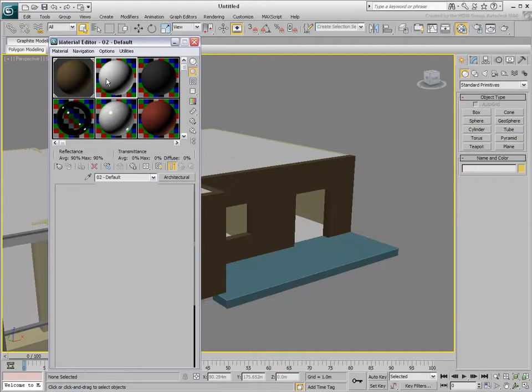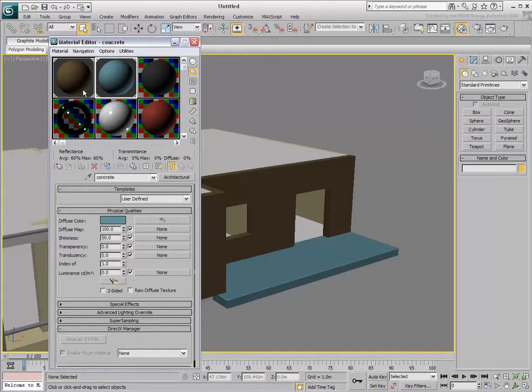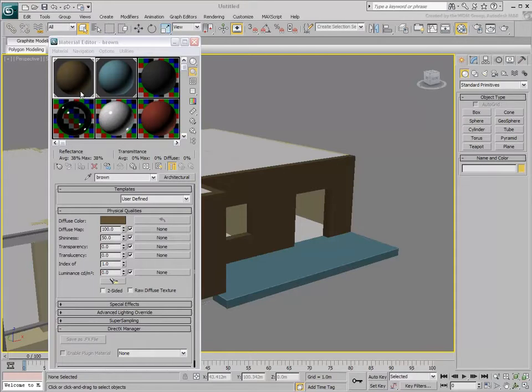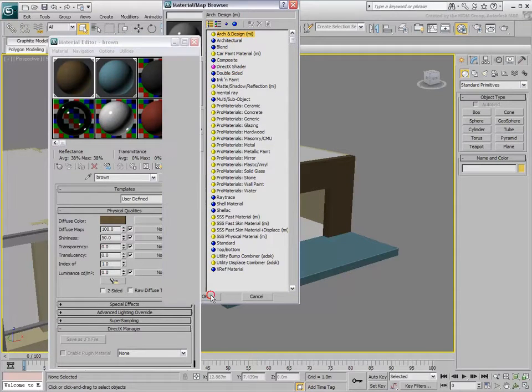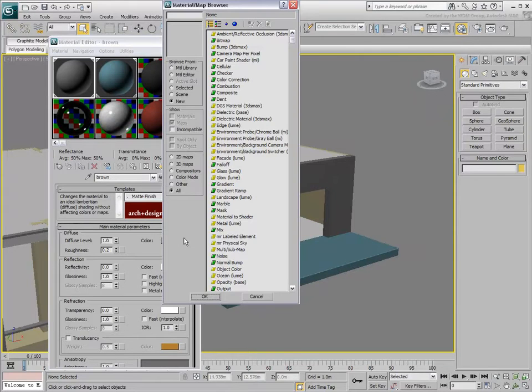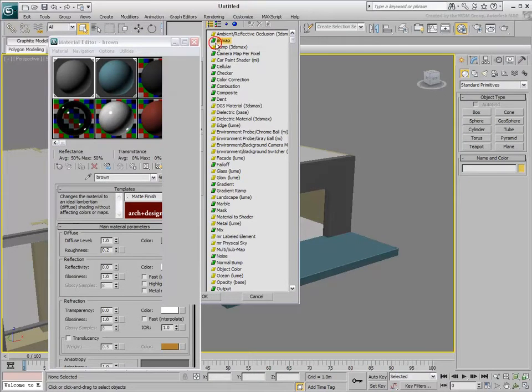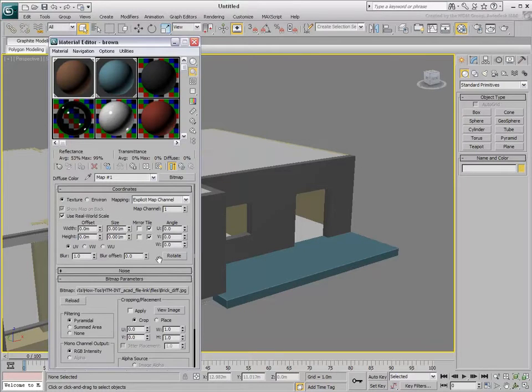In design renderings, you usually use the Mentor rendering engine with physically accurate materials. This means you need to edit the materials coming from the DWG file. You can turn them into Arc and Design materials and choose a base template for them. You can also apply texture maps to the various channels in the material. Some templates may already contain texture information, but you still might need to fine-tune their values.